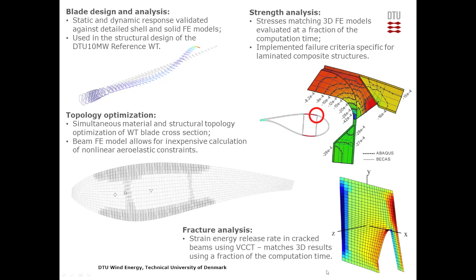Finally, the last work we have done is on fracture analysis. So we use the virtual crack closure technique to calculate strain energy release rates on cracks in the cross section. And once again, we see a very good match with 3D results for all three crack modes.